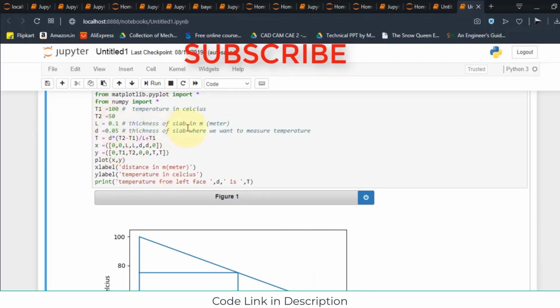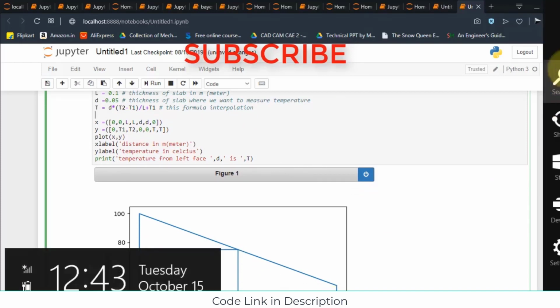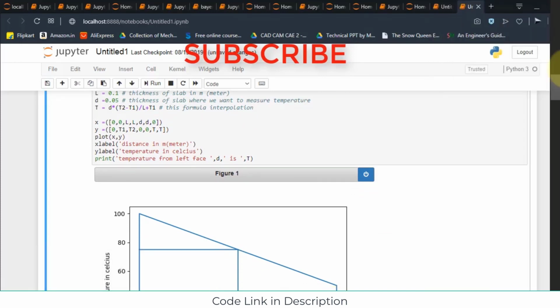L is the total thickness of the slab, 0.1 meter, and D is the distance into the slab where we want to measure the temperature. Remember, this distance is taken from the left side. Just remember the convention. Now this formula arises from interpolation. For those who don't know how this formula arises, let me show you how this works.